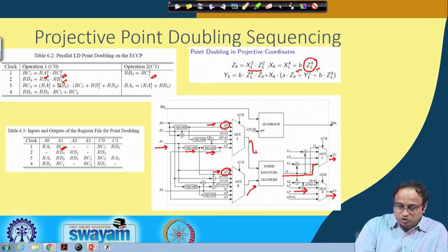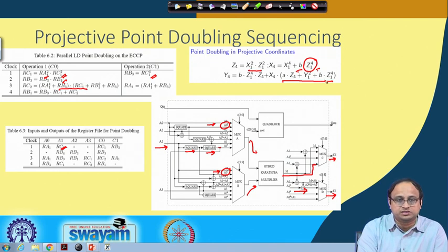Likewise, you also need to calculate Y4, and you see that the computation of Y4 has more than one multiplication present. So for this computation we require more than one clock cycle. What we do now is that in one clock cycle we compute this part, which is your RC1 plus RB1 square plus RB3, which is computing this part. Remember, A is equal to 1 in this design. The other part, RA1, is computing your RA1 to the power of 4 plus RB3.